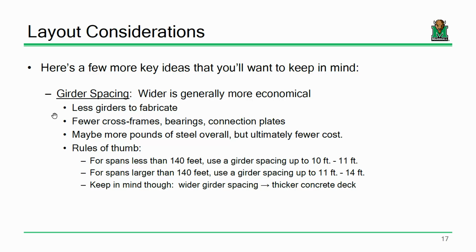You have to spend a little bit more time and effort investigating fracture critical bridges because if one of those main load carrying elements fails, you've got some problems. Now, it's not super codified in the spec, but the way that the spec is geared and written, generally if you're using 4 beams or more, you do not have to worry about fracture criticality.